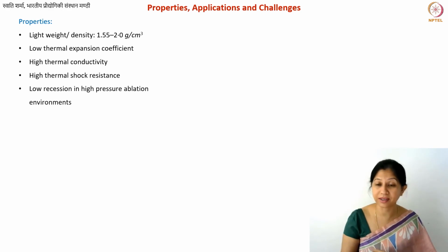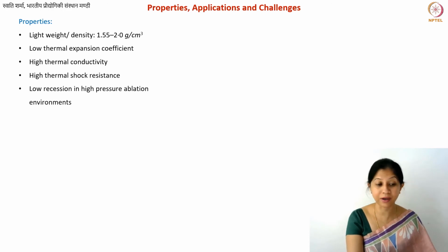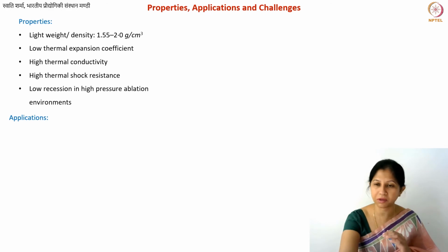Okay, you can also perform a range of manufacturing techniques and processes with these kinds of materials, which you could not do with carbon fiber reinforced plastics, because there again thermal properties become very important. You had very different thermal conductivity of the carbon fiber and the polymer matrix. So it becomes difficult whenever you're performing any manufacturing operation. Whenever your polymer goes above the glass transition temperature, it's difficult to machine it. But that is not the problem with carbon-carbon composites, because we have very good thermal properties of these materials. So when you're doing manufacturing, the kind of heat that you generate by drilling or milling is not going to do anything to your carbon material.